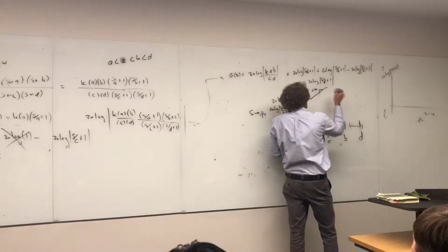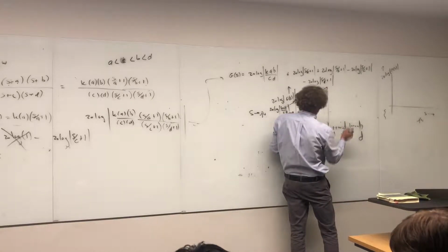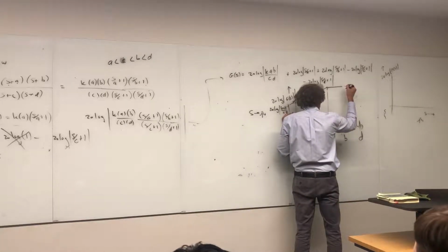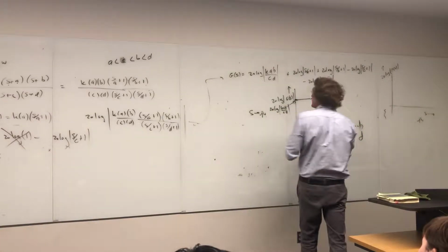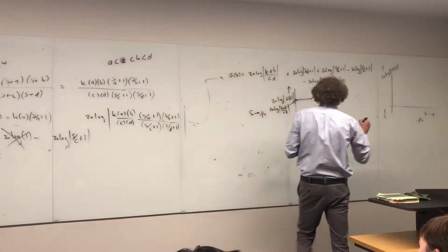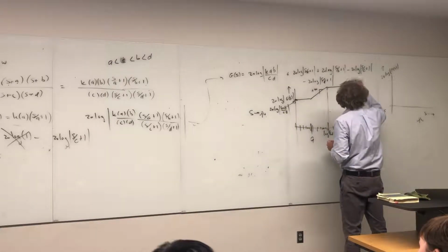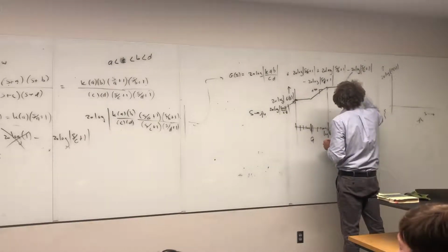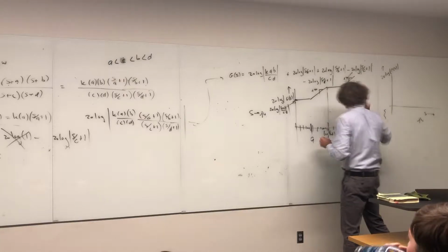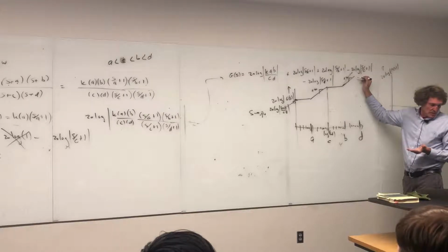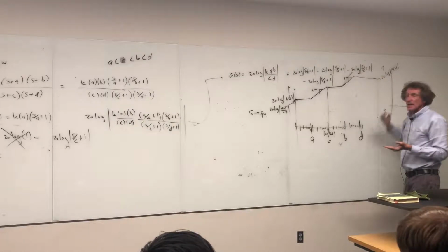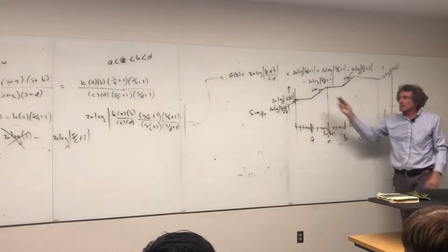So it's going to stay at whatever value that C is at until it hits B. And then at B, I said that B was greater than C, so then it starts going up again at 20 dB per decade, right? Until it hits D, and what happens at D? Just stays flat.